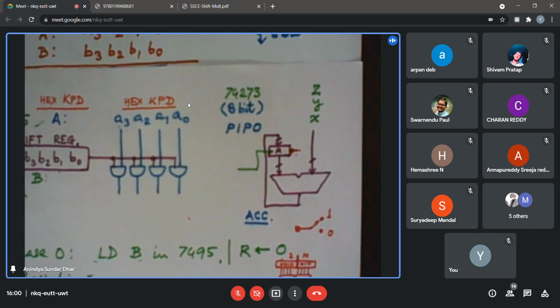If the line is green, what does it indicate? The value is 1 for that line. There are 3 possibilities: green, blue, and red. One might be 0, one might be 1. What about the other one? That is a tri-state or floating or unknown. Before starting the simulator, you may find it remaining green or something, so you do not know what it is. Anyway, you can use all these debugging mechanisms, whatever you feel like.